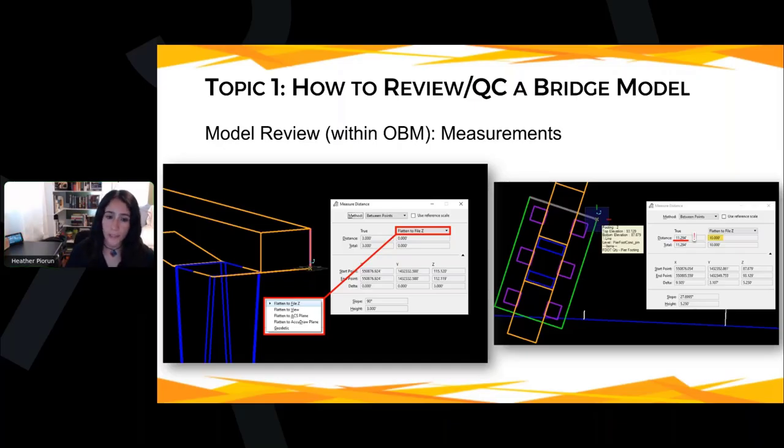But there are ways to control against that, and ways to make sure you understand what you're clicking on. One is level management that we just talked about. If you don't care about the 3D stuff, you can just turn it off. If you don't care about the 2D stuff, you can turn it off. And another is these options to flatten to file Z or flatten to view. You can use those. So these are your options here.